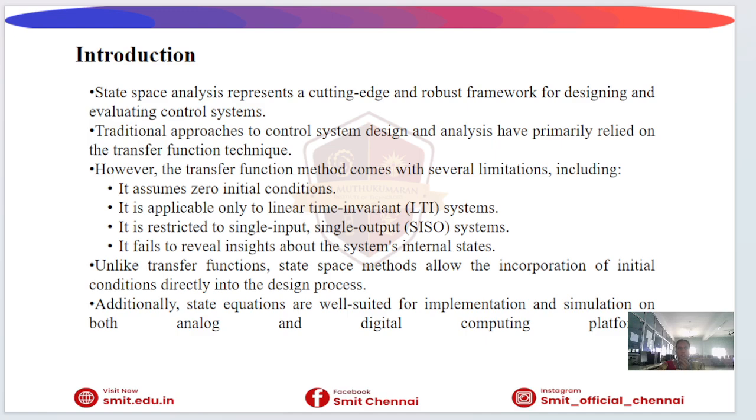The limitations of the transfer function methods: it assumes zero initial conditions, is applicable only to LTI systems, and is suitable mainly for SISO systems, single input, single output systems. It does not provide information about internal states. State space analysis overcomes these limitations, and it is suitable for computer based simulations and modern control designs.